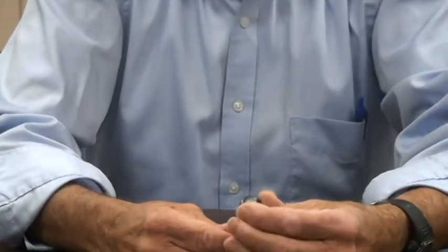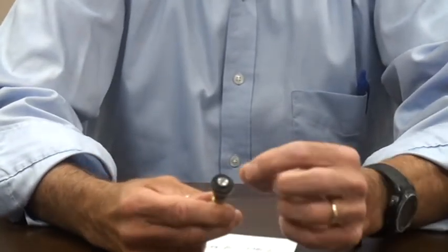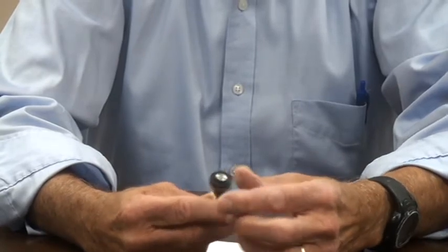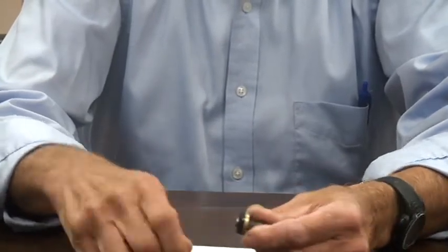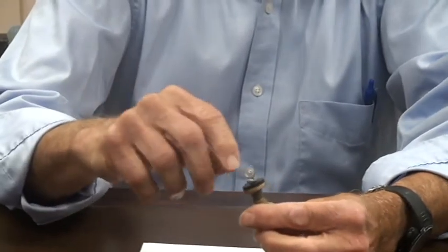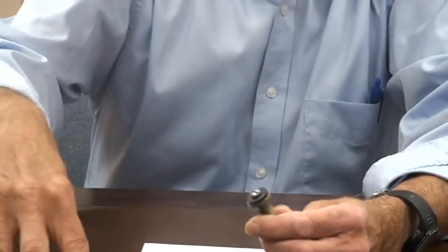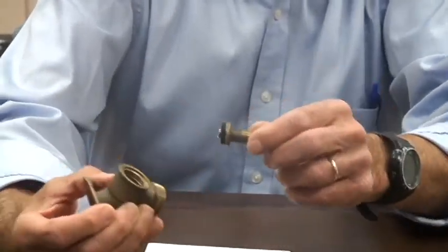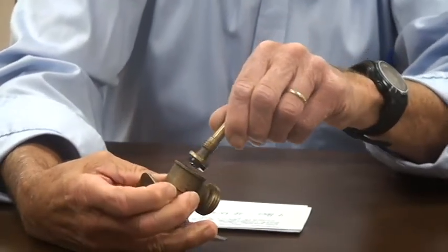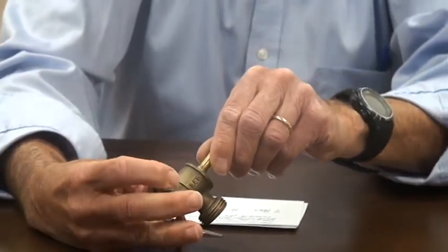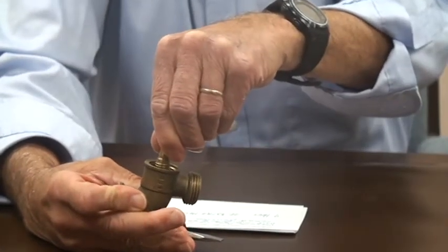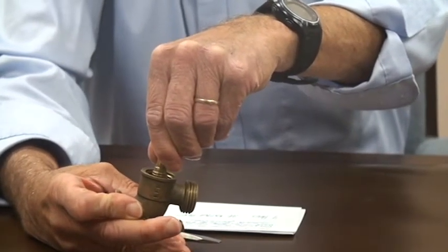So what we have here is the valve stem, which really can be disassembled into three pieces. At the bottom of the valve stem is a rubber washer that's removable, and if this washer wears out it can be easily replaced, and it's held in place by a screw. So in the functionality of the faucet, this rubber, called a faucet washer, not surprisingly, when you screw the valve down, bears against the machined portion of the base, and that's how you seal off the water flow to the hose.